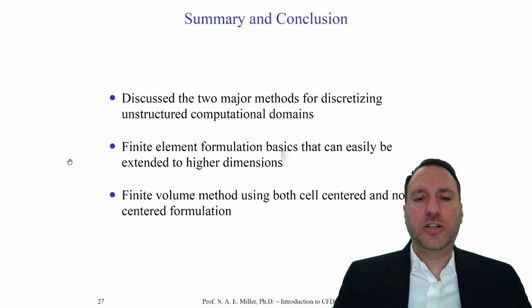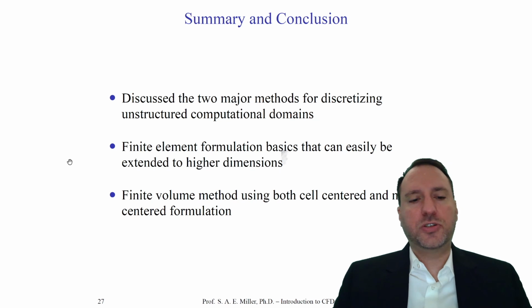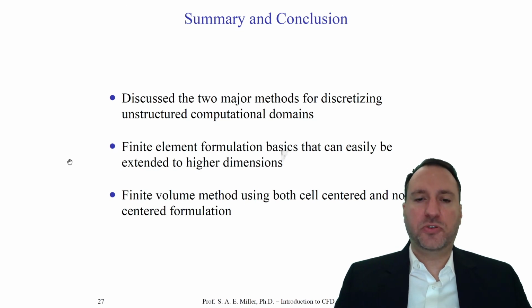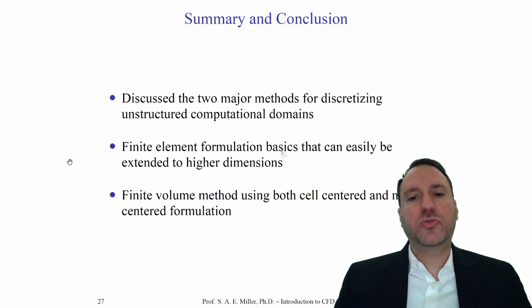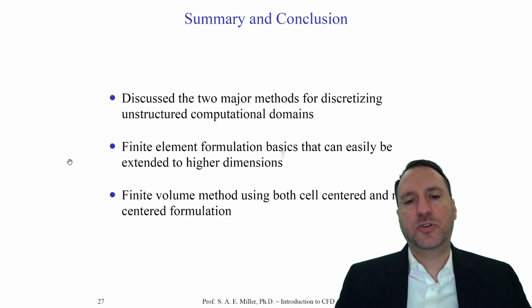A major advantage of the finite volume approach over other approaches will, of course, be that it conserves all the variables we're solving. It'll conserve mass, momentum, and energy throughout the global domain and locally, because it's strictly enforced and directly accounted for through the fluxes of neighboring volumes. This is exactly what you've done in a simplified way for a single volume element in your fluid dynamics classes.